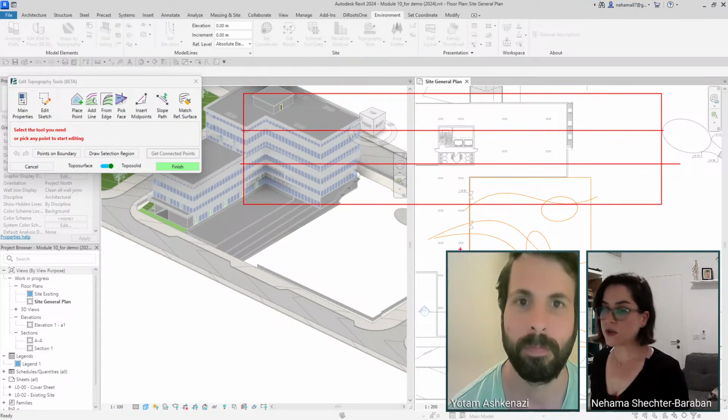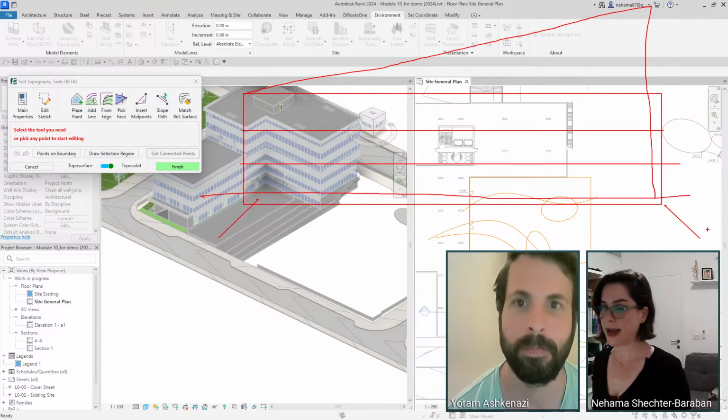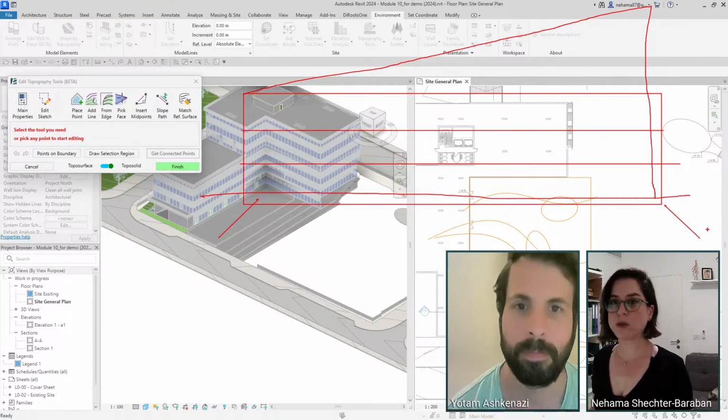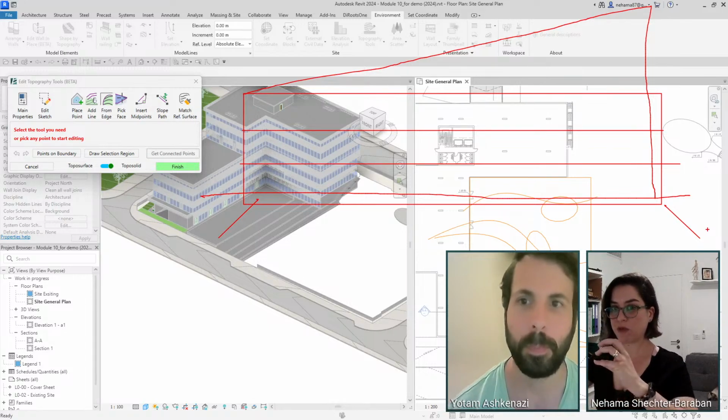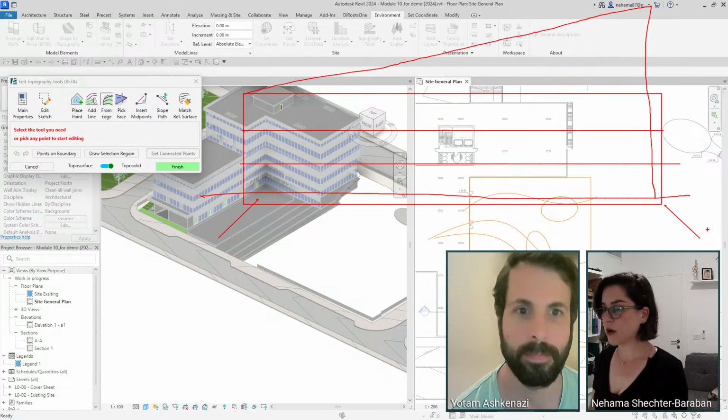But if you use a floor with a variable material and you lift one of these up, then you'll get something like that. So the bottom part of the floor would always stay attached to the original placement level, and the volume would just increase, would just get bigger. And that's a variable material.